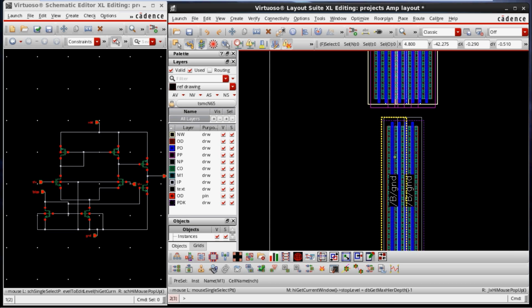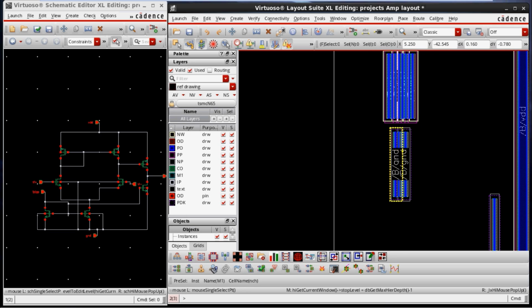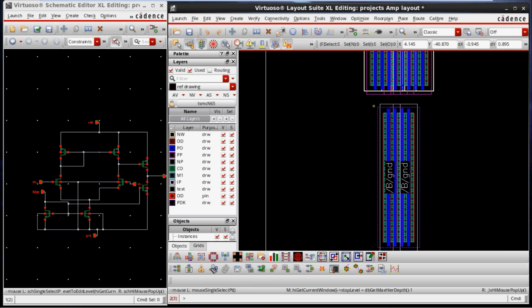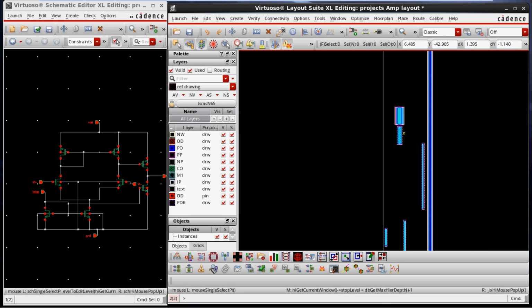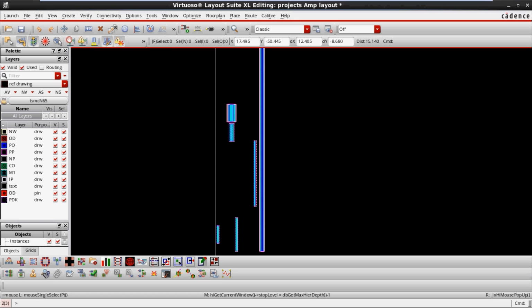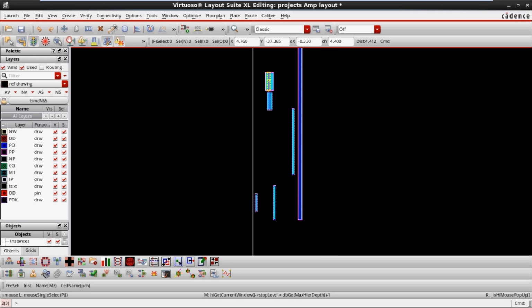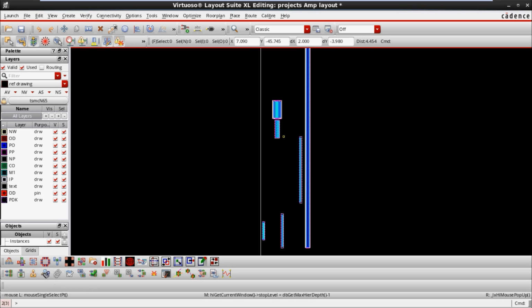The differential pair is not matched yet, because we have only two devices. Usually I take W as 4.8 as a common number, so that we can go for multiple layouts, no issue. This is just one kind of floor plan, we can go for multiple floor plans.